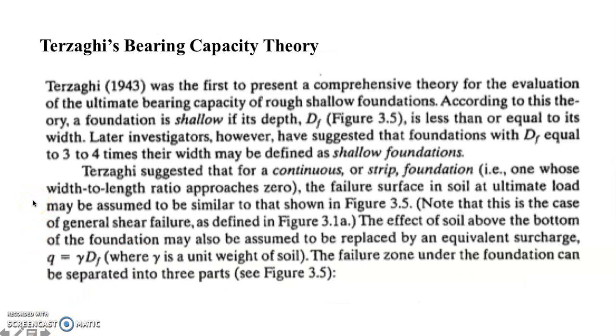We move on now to Terzaghi's bearing capacity theory. Terzaghi, in 1943, was the first to present a comprehensive theory for the evaluation of the ultimate bearing capacity for shallow foundation. According to Terzaghi, a foundation is shallow if the depth D sub f, the depth of embedment of the footing or the foundation, is less than or equal to its width. So that is a shallow foundation.